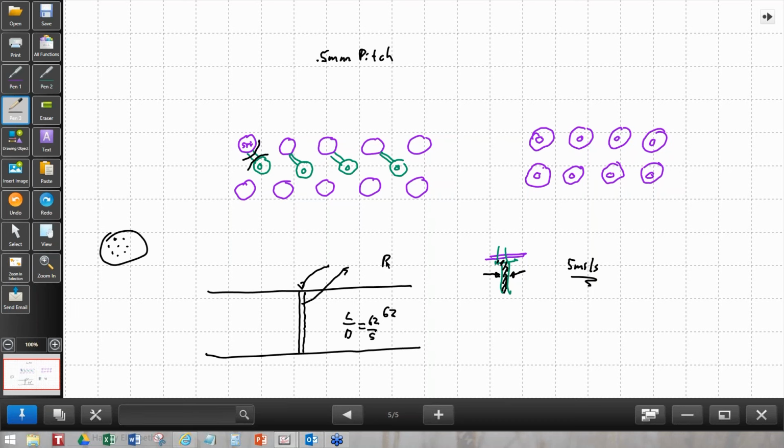Well, they typically put pressure up here and a vacuum down there. Oftentimes they'll use a rotating squeegee on the board to try to push it down the hole. Well, if you've ever tried to put large rocks into a pipe, you'll find that they jam up. That's exactly what's going on here, especially if the surface texture of the via barrel isn't perfect.